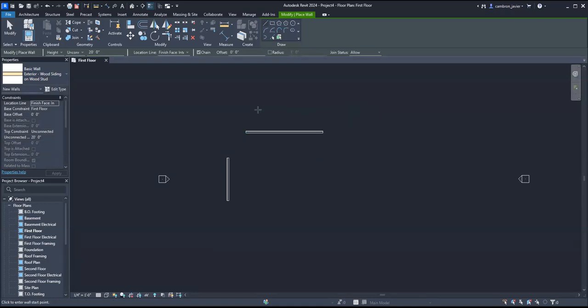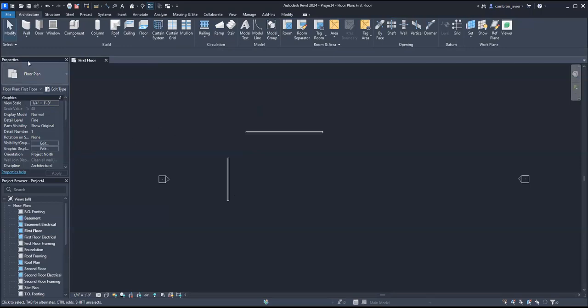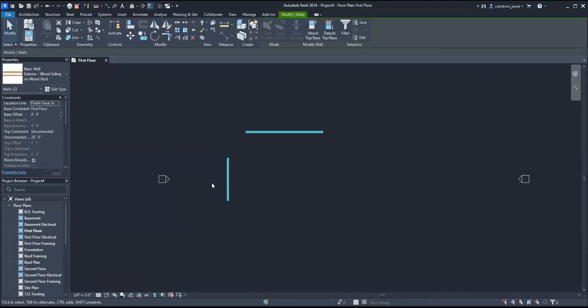If we hit the escape key a second time, it takes us back to the default layout, where we could start making additional changes. So if you ever feel stuck, in the middle of a command and you have no idea what you're doing and you want to get back to the original default settings, just keep hitting that escape key and it'll eventually bring you back here, okay?